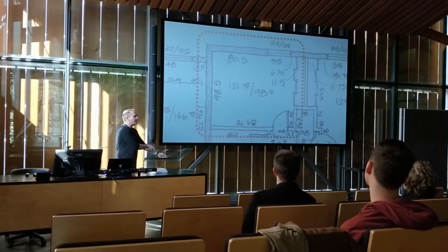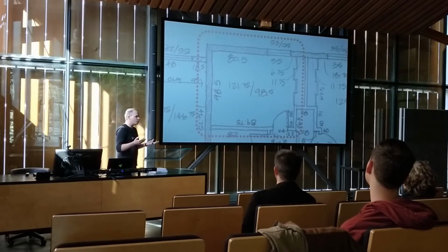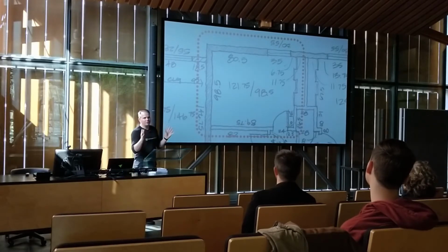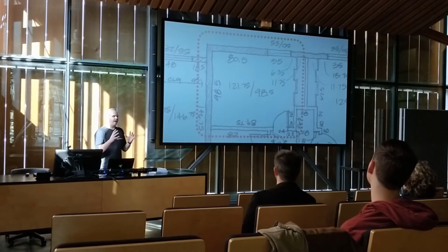I can tell you that no matter how meticulous I am, there will be some discrepancy of a couple inches. It'll just happen. In these old houses, especially this one in Denver, built in the 1920s, there's always something out of true, and it'll drive you nuts trying to make it come together. So if I just get the X and the Y, I can go back in and have a check to make sure that, or if I just goofed up on a dimension, I have an overall that keeps everything lined up. So that's another helpful tip.